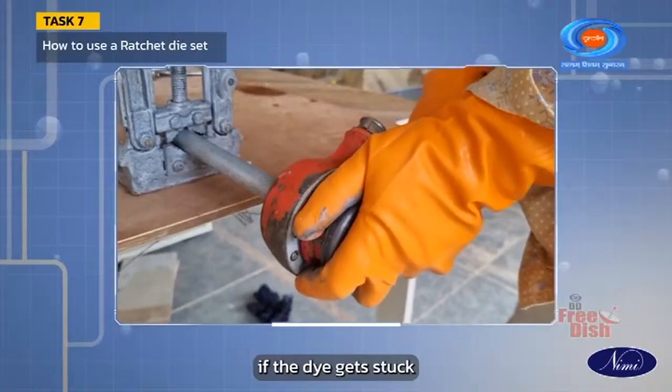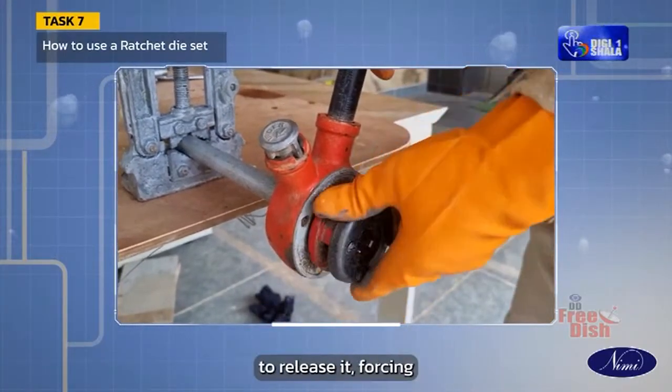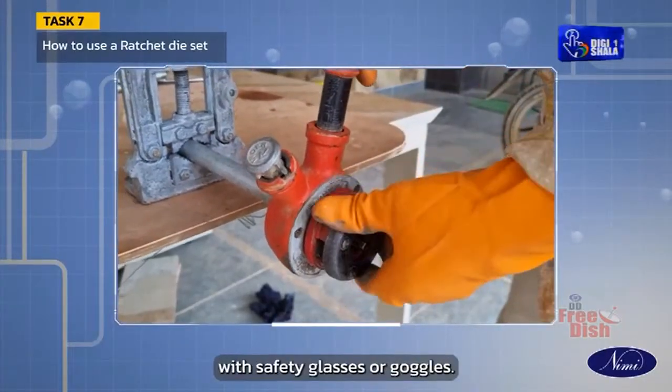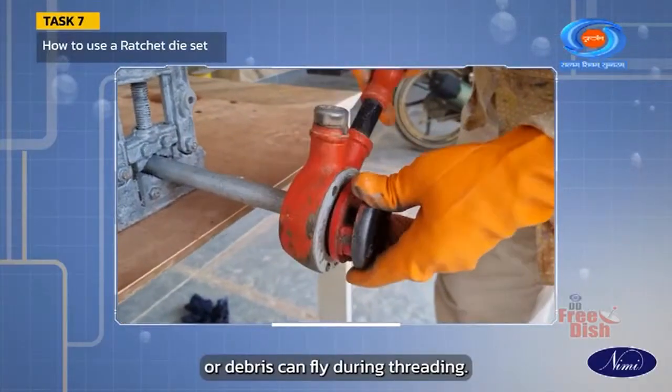If the die gets stuck or encounters resistance, reverse the ratchet slightly to release it. Forcing it can damage the threads or the tool. Protect your eyes with safety glasses or goggles. Metal shavings or debris can fly during threading.